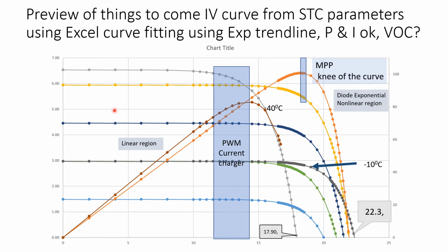It depends on how bright the sun is, time of day, time of year, how much stuff is in the air between the sun and your solar panel: water vapor, gases, dust, and all the other gases up there that really don't do a whole lot as far as diminishing the amount of solar radiation you got, but it scatters it, so effectively diminishes it.